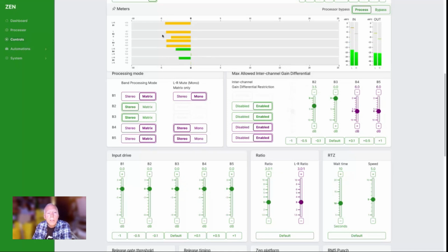If you go to where you allow a little bit of flexibility between left and right channels, there may be a stereo shift possible, but that's probably not that big of a deal if you're keeping the amount of allowed difference to be less than 5 or 6 decibels. For the controls that are in the matrix mode, you can see that we're in mono for the first band, so there's no gain restriction there. But for the top 2 bands, which we're using in a matrix, you can see this -6 tells us that the left minus right can never increase more than 6 decibels in gain above the left plus right.